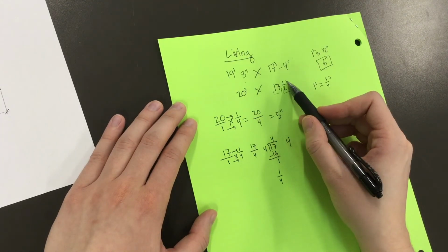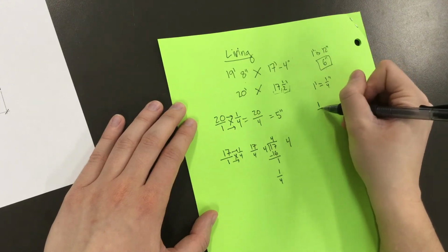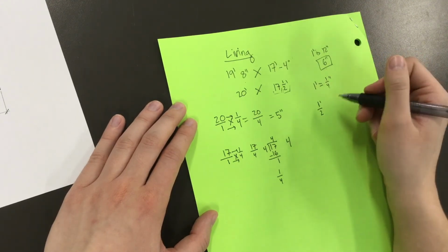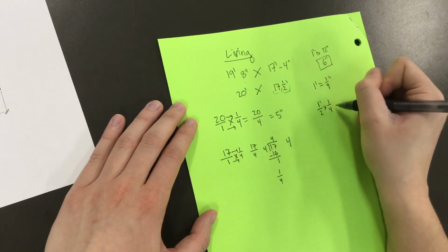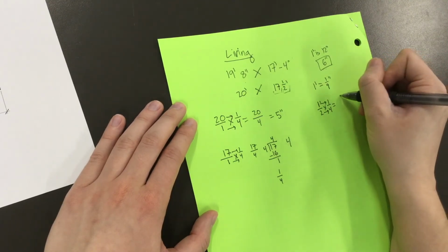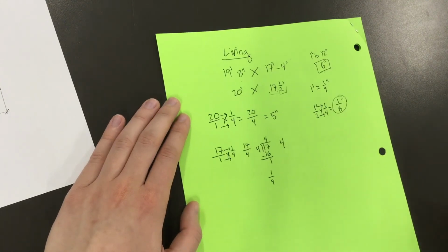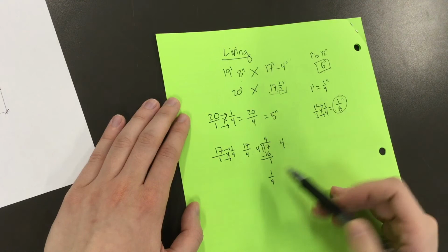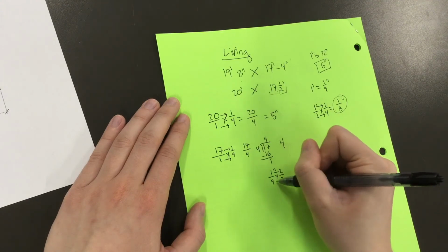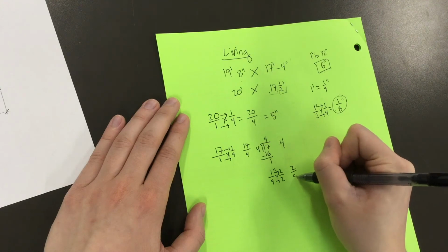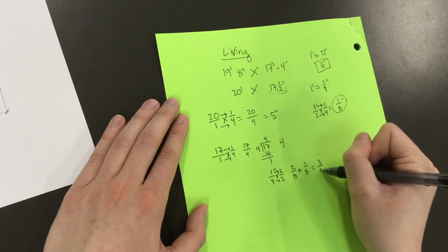So we're looking at 1/2 of a foot. So basically we're looking at 1/2 of a foot, and that's supposed to equal 1/2 of a quarter. So we're just going to multiply these together. Multiplying straight across means we have 1/8 of an inch that we would draw for this 1/2 foot. But we need to combine this 1/8 of an inch with our 1/4 inch, and to do that we need common denominators. So we have to multiply this by 2 on both top and bottom to give us 2/8 of an inch, which then I can add easily to my 1/8 of an inch, which then means I have 3/8 of an inch that I would draw for that line.